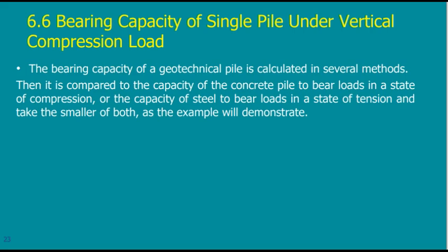But I studied the pile. Actually, I did not study the pile. When I study the pile and say that the capacity of the pile is so and so, I am defining what? I'm defining the soil. I'm saying that this layer has C and phi, and this layer has C and phi, and this layer and so on, and I calculate something and I tell you that the pile can carry this amount. Actually, this is not the carrying capacity of the pile. It's the carrying capacity of the soil to carry the pile.